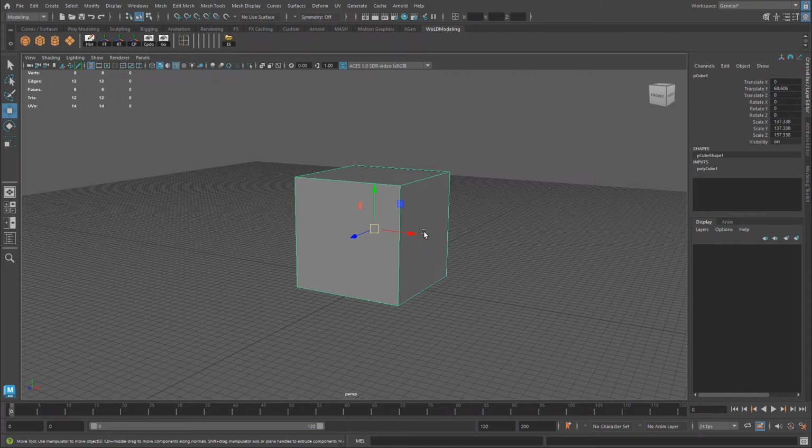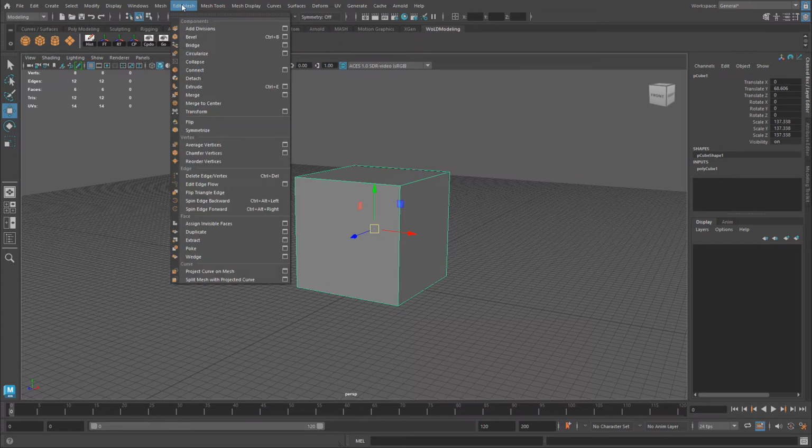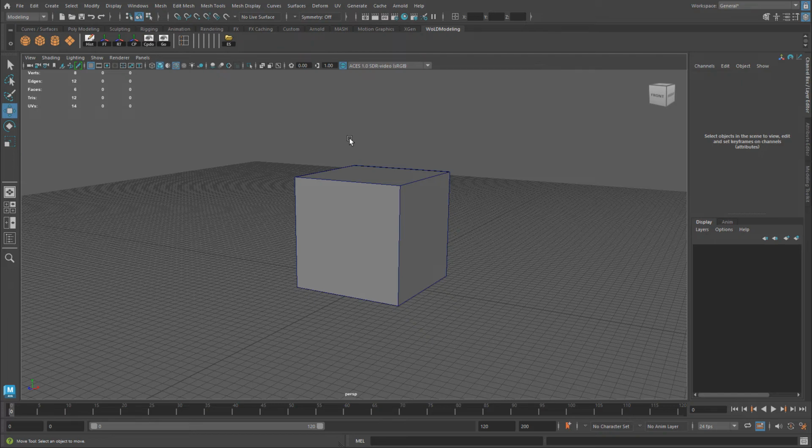You will find many default shortcut keys whenever you use the drop-down menu for anything. Just always note that if you are continuously repeating something over and over again, there is a shortcut key. For example, the modeling tool bevel has Control B, extrude, Control E. Some of these will always list something that you can use right away. I personally do not like using custom shortcut keys or setting them myself. I like to use the default. This way, if I ever jump over to another version of Maya on another computer, I'll be able to use whatever is there right away without having to find my settings, find my shortcut keys, and import them into work. So I always use the default.